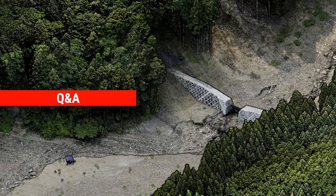The relative accuracy is a measure of how well overlapping passes match each other. So it's really giving you a comparison of the offsets between each flight line and any that overlap it. And then the absolute accuracy is a measurement of how well your point cloud data is matching the surveyed ground points that you've specified as independent checkpoints.